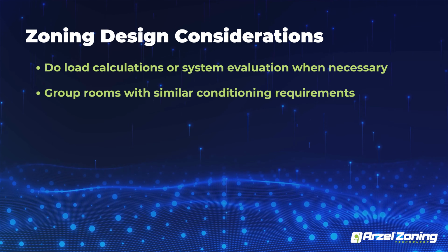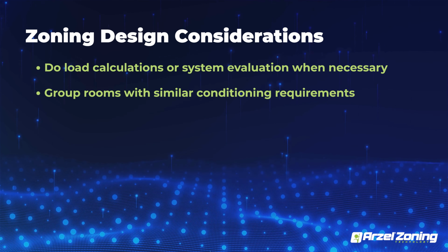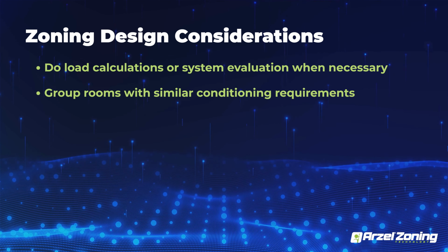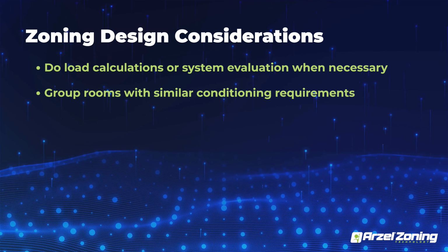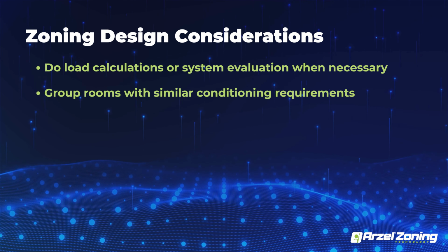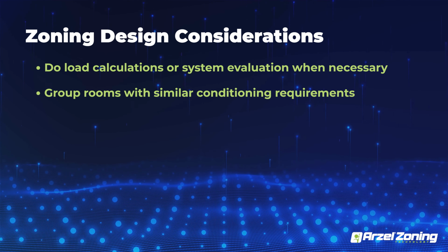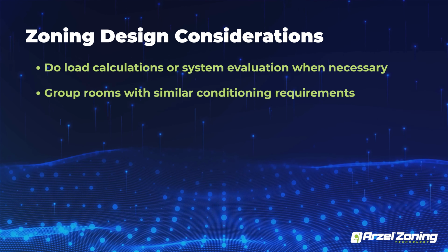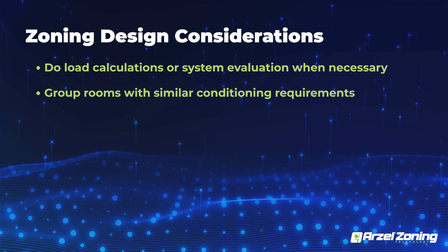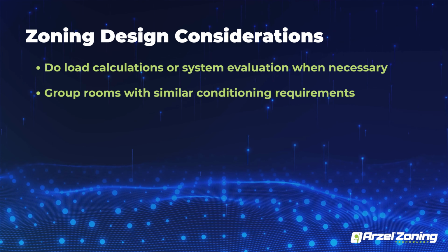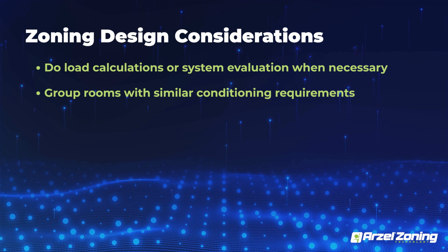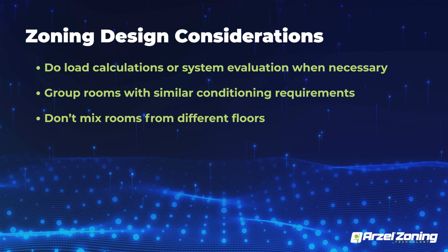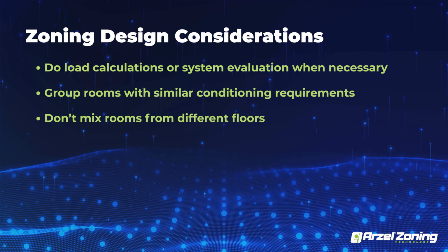So you don't want to group rooms where this room is totally comfortable, but this room is so warm during the summer. Maybe not consider pairing those 2 rooms together in your design, right? What other rooms on this level are similar to this room? Well, these other rooms over here on this east side of the home are very similar. Group those rooms together. Never take rooms from different floors, first and second floor.